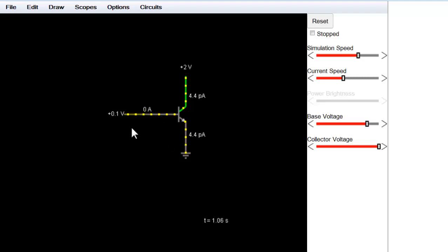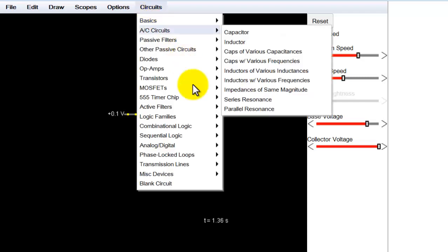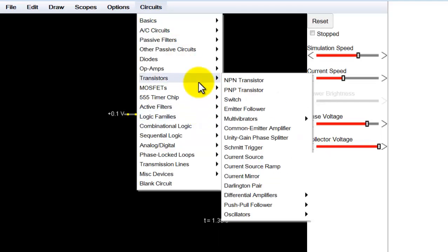So this can be operated as an electronic switch with the help of a microcontroller, and the controlling logic can be given by the microcontroller, while the supply that needs to be given to our device, depending upon the controller logic, can be given through the collector or through the emitter. There are various configurations in which this can be done, like the common collector configuration or the emitter follower configuration. Now let us actually see a PNP transistor.